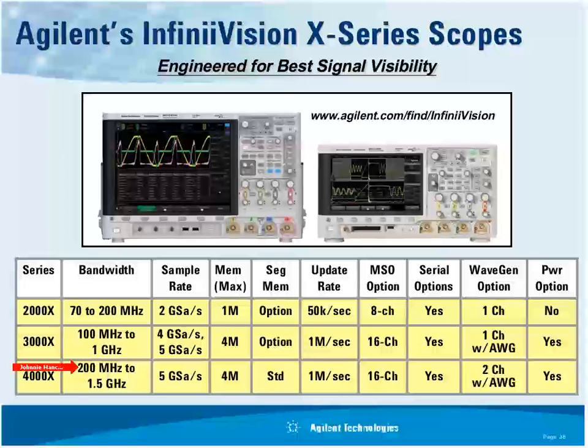The switching circuitry might be going up to a few hundred kilohertz. Again, you don't need a lot of bandwidth to measure that. However, it's the transitions, the switching speed of those switching devices, the rise times and fall times that are important. That's why you might need 100 to 200 megahertz.